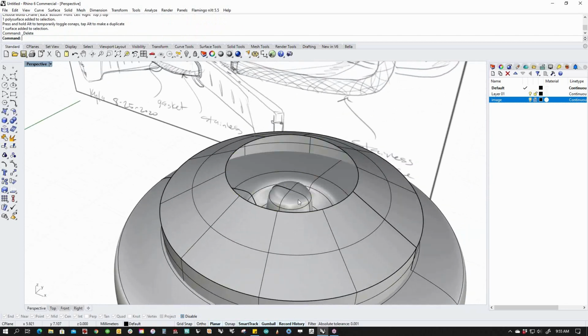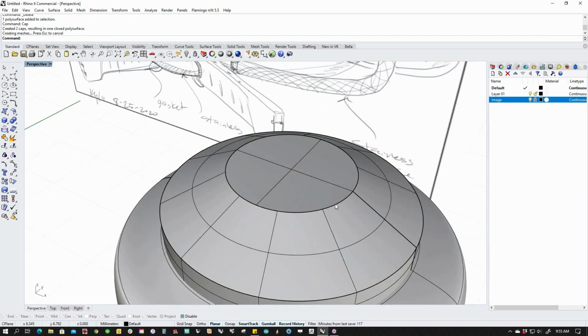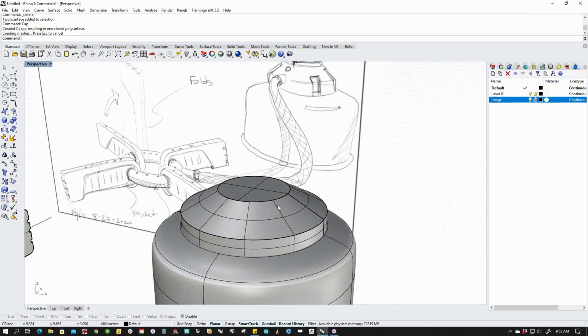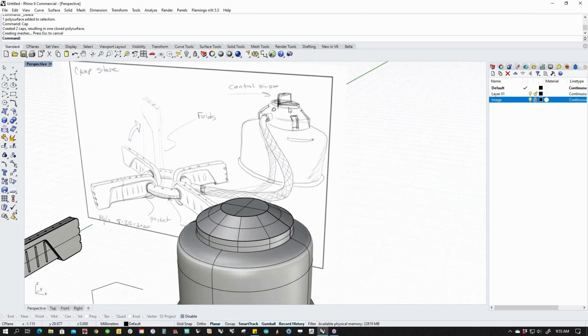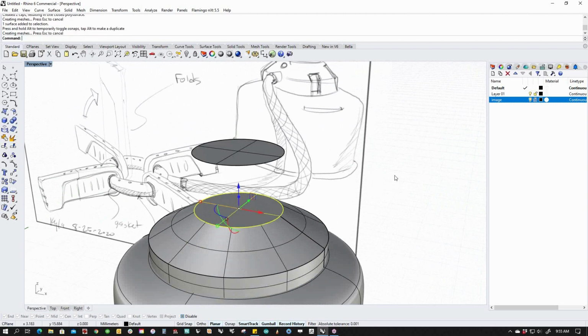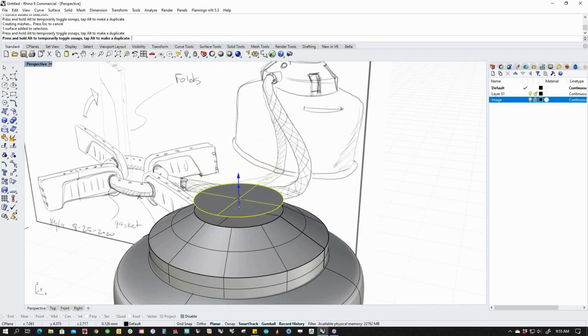And then let's do something more fun. Let's get rid of this. And then I'm going to run the cap command, which gives me a flat cap, which doesn't have that radial seam in it, which is more fun for building things. And I need to build a little separate piece on top of this. So shift control click, drag, tap alt. That breaks off a surface and makes a new piece. I'm going to position it right there. Extrude it up.